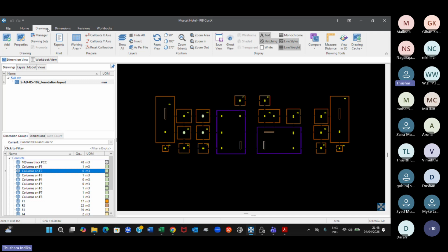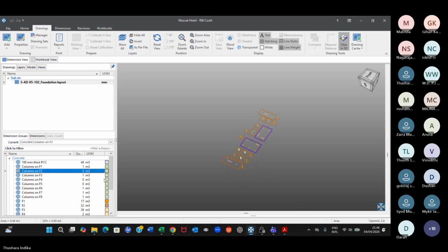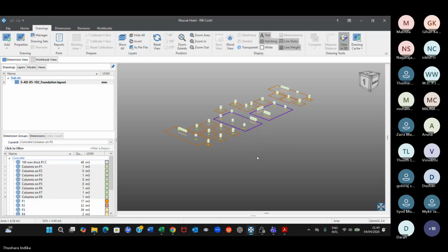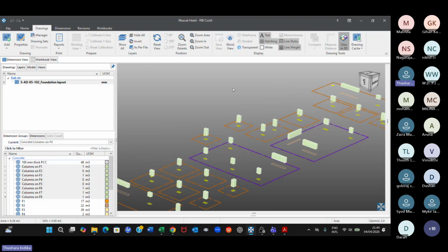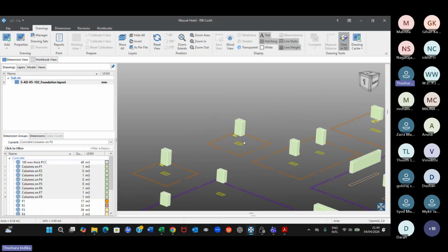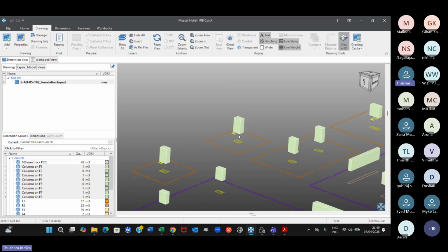For that, you go to drawing and say 3D view and select everything. You get full, or you can select if you want only this part, only the column that you have measured, right? You can see you have measured everything, isn't it? It doesn't give you why these columns are located a little up because, can you remember, I have assigned certain offsets to accommodate the fact that these columns are sitting on top of the footings.